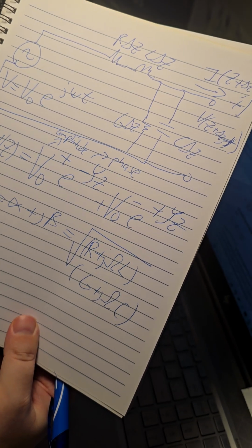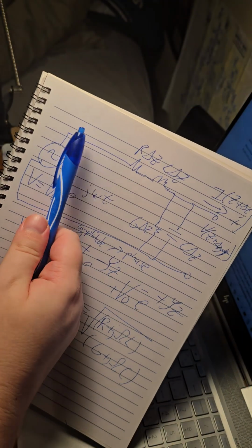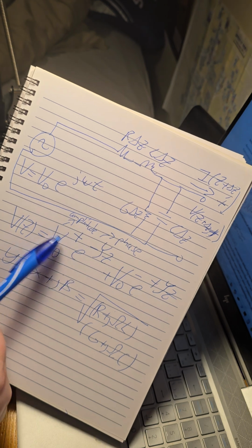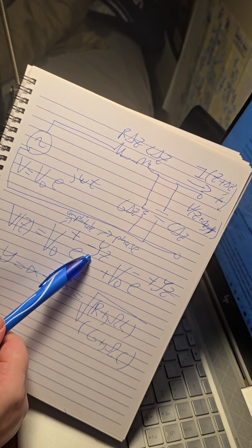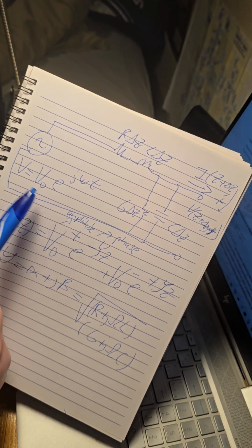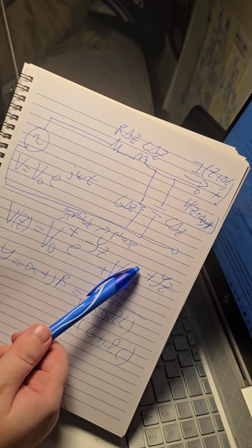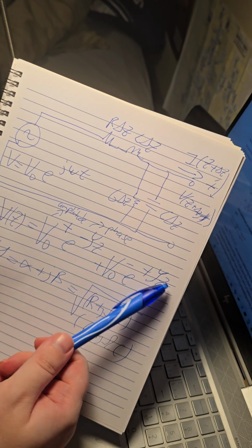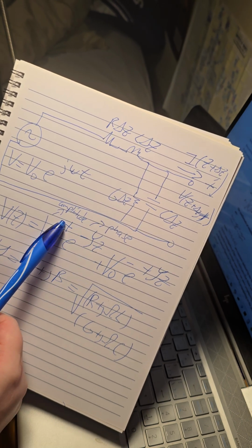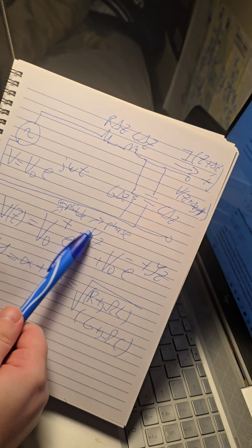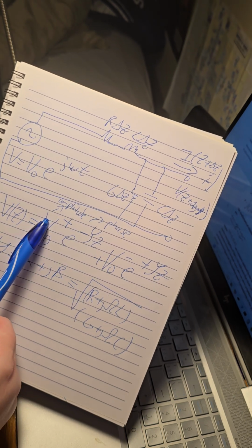And yeah, so anytime you want to find out where you are on the line, you go to this formula, plug in your z, calculate the phase. Your amplitude comes from the amplitude of the source, and then you will get that. Now, not only is this the phase, but this is also scaling the amplitude, because the real component of this will affect the amplitude.